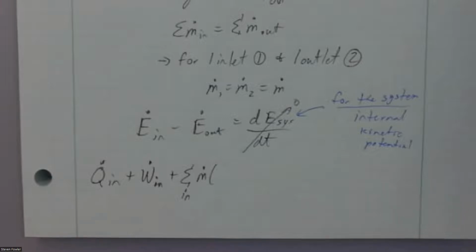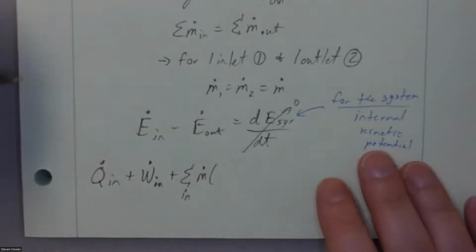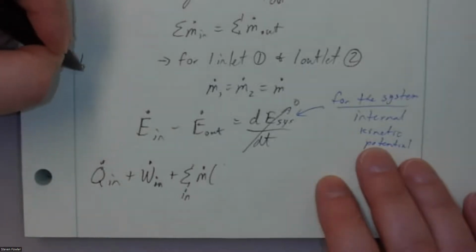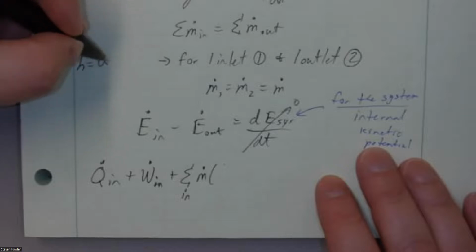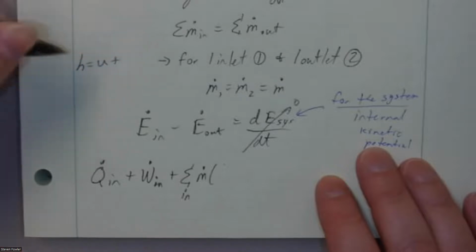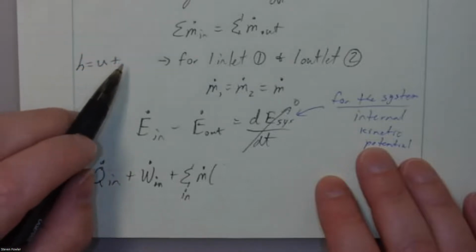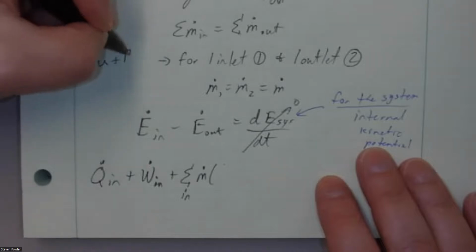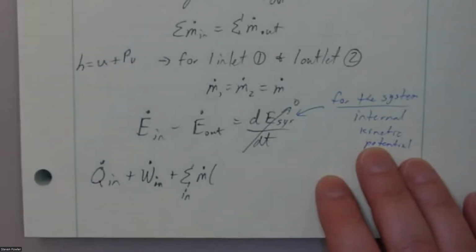But because it's flowing, something has to push that energy to flow. So we're going to use h's because that mass has its own internal energy, but it also has the energy of the fluid upstream pushing it out of its way.